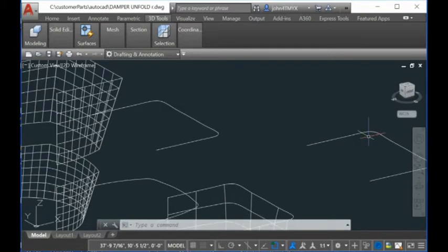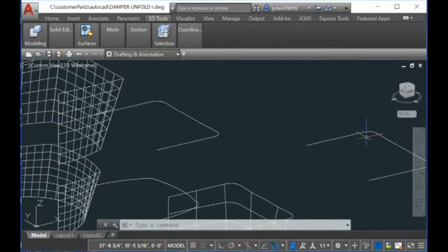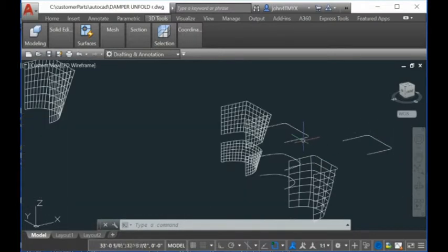Most of them you have to have a fillet in order to bend it. Okay, and make sure that you have fewer control points. I don't know whether you know about B-spline curves and surfaces, but if you use fewer control points, it's going to be easy for you, and the accuracy is going to be high.